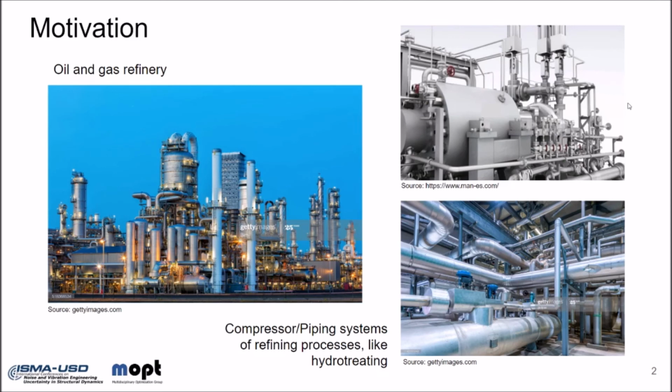In oil refinery plants, the structural vibration behavior of gas pipeline systems can be strongly affected by the response of the acoustic domain represented by the gas being transported through pressurized pipes, cylinders, and other related components. In the hydrotreating process, for example, hydrogen gas must be pressurized to high pressures. Large reciprocating compressors are used to reach this objective. The gas pulsation produced by this kind of machine is an important source of excitation for the pipeline system.